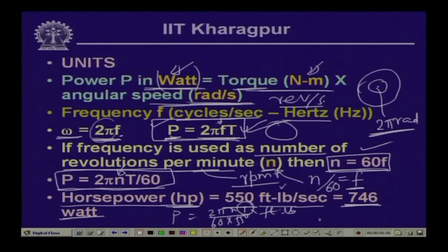So, this is helpful in relating the transmitted power and the torque, and so when we like to find out the diameter of a shaft which is necessary for transmitting power from one device to the other without exceeding the level of stress, first we compute the amount of twisting moment that is generated in that shaft for transmitting that amount of power.